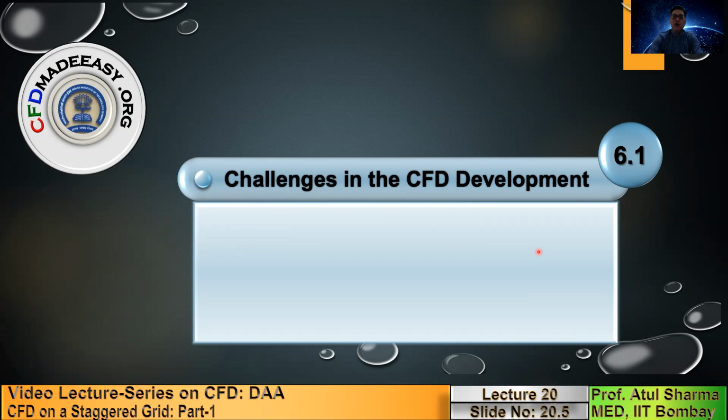Now when we are moving from computational heat transfer to computational fluid dynamics, note that there are 2 additional laws which now will appear for this topic. Those 2 additional laws correspond to the mass conservation law and the momentum conservation law. If you compare the energy conservation law with the momentum conservation law, you should note that the energy conservation law is a scalar law and the momentum conservation law is a vector law.